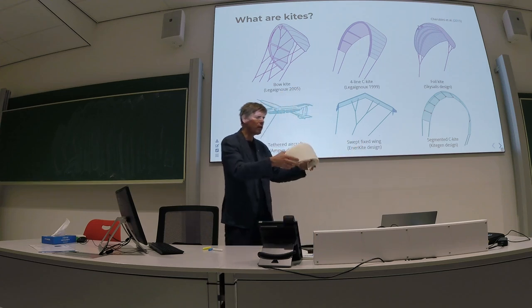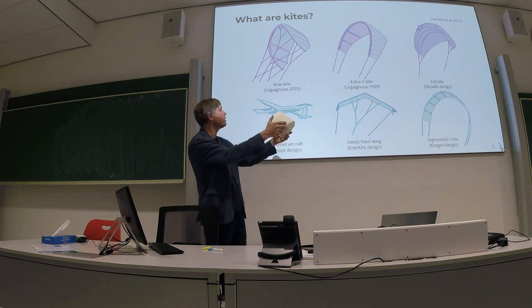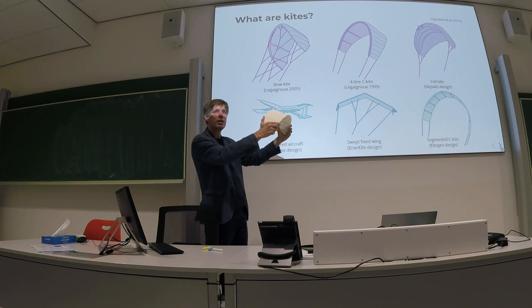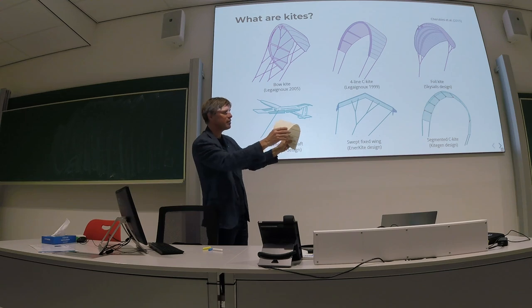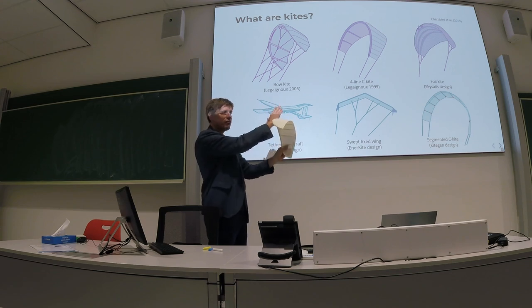It goes a little bit too far, but since I'm already talking about it, the bow kite also twists the wing, and in this way creates a steering moment. The sea kite also does that, but the Sky Sails kite just rolls the entire wing with these 2 lines, and in this way rolls the lift vector.